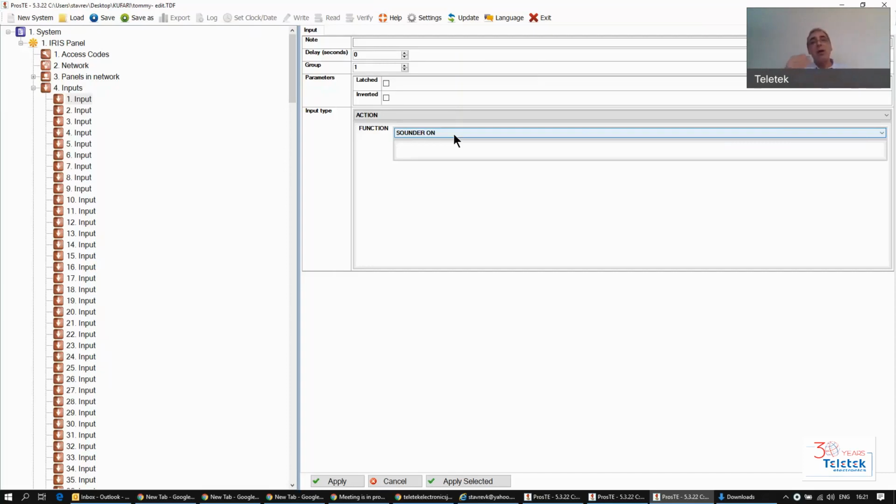This is when you want to activate some relays to send elevators down, open doors, fire escape doors, or other bells or whatever. You don't want to activate them before that. That's why I'm saying sounders on is probably one of the most used logical inputs that you can create. An input that monitors the sounders. In case the sounders go on, then you can trigger different events or different modules in the system. So let's go through the process of designing an input.